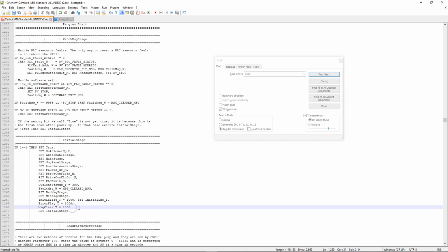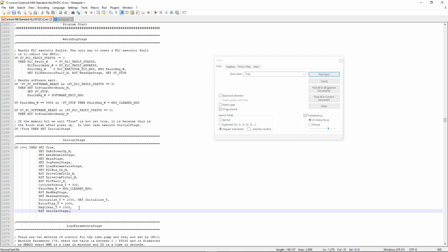So you need to make sure that if you're having multiple things, each one is separated by a comma. And if you accidentally put a comma on the last one, the PLC program will also fail on you when it goes to compile, because it's looking for the last item and seeing that there's nothing there. So it'll keep going down, and it'll see this and say, I don't see that as a set. I don't see a reset. I don't see anything in front of it.